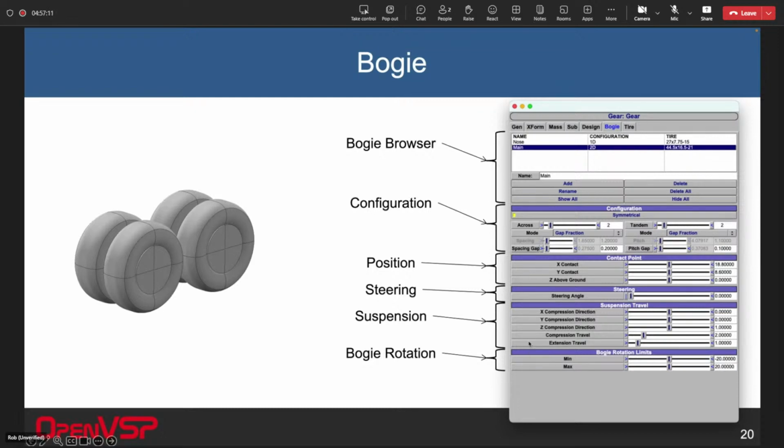The strut deflection, it's a very, very simple model of strut deflection. All it is is a direction vector, a magnitude of compression, and a magnitude of extension. And that's how we model, in this case, how you specify what the gear travel and the strut compression and extension is. It's just a vector and a magnitude in each direction. Same vector, different magnitudes potentially.